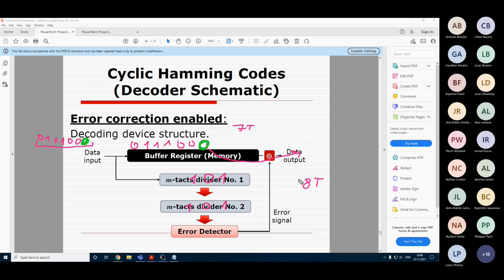And this is our only opportunity to actually correct the symbol, because at the next step we will be reading this symbol and this will be already gone. So now we need to correct the error when we read data. We read this 0, and this error detector generates symbol 1, which accordingly inverts this 0 into 1. Now imagine the situation that we have the error not in the first position, but in the second position, here.